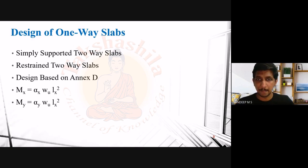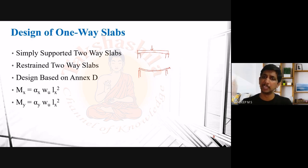So basically, if you are considering the side view of these slabs, say your simply supported slab will be like this. You will be having the support, and the slab will be simply resting on this. This is simple support. Okay. So once you subject the slab to loading, you again will have these supports here. This slab will bend like this. This is an exaggerated figure, so don't expect that you will be seeing this much gap in actual structures. Okay. So the ends of your slab will be free to rotate. That is the main thing. If you see the end, it will be free to rotate.